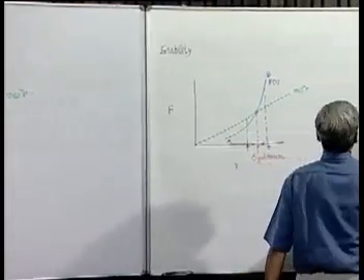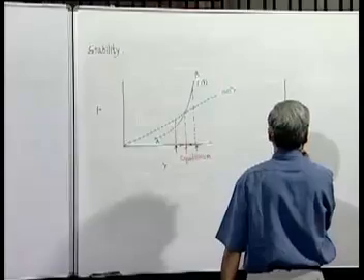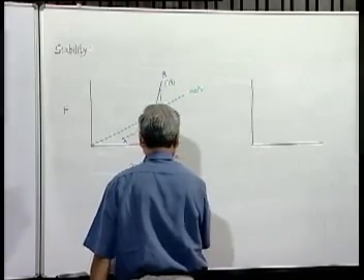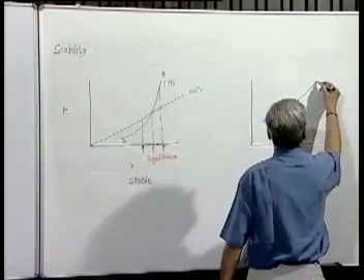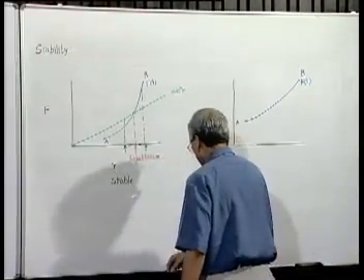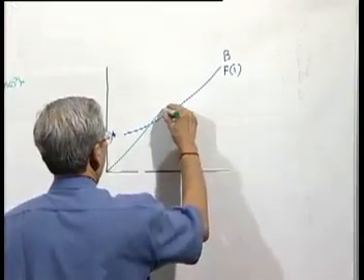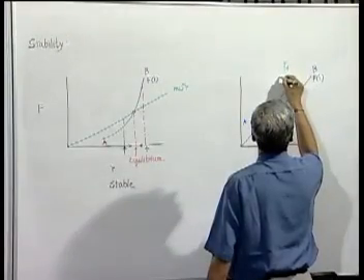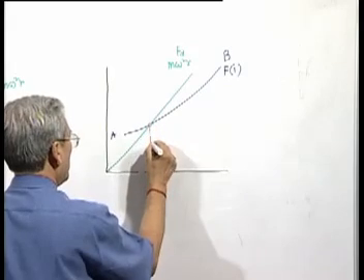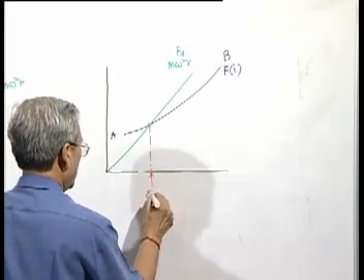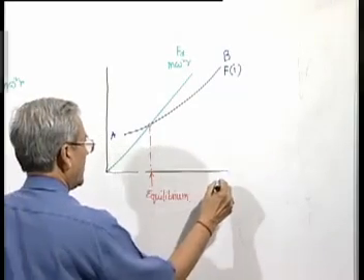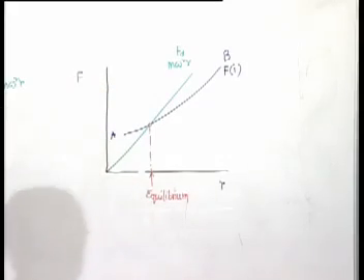On the other hand, so this is stable. Here, this is the control force diagram, and now for a particular speed omega, this is the deflecting force m omega square r, and obviously the equilibrium position is where the deflecting force and the control force are equal, so it is running in equilibrium.